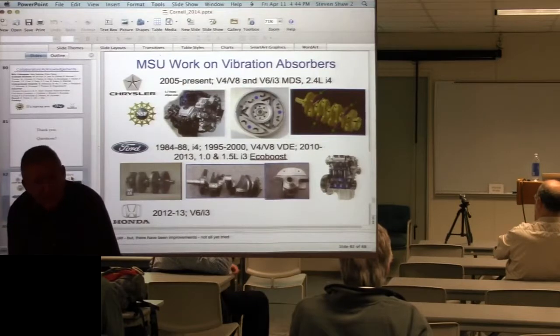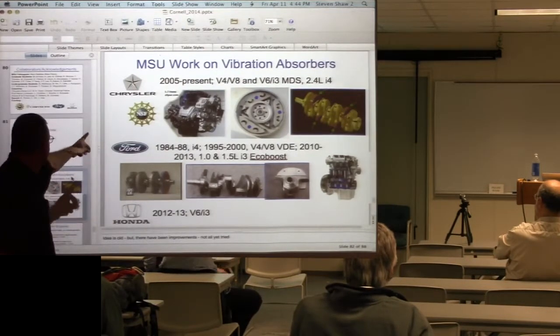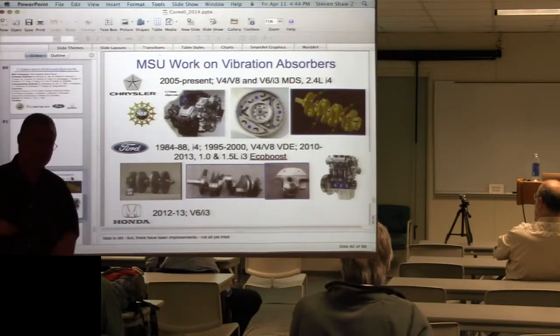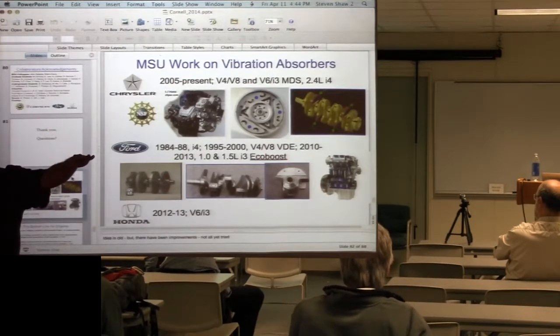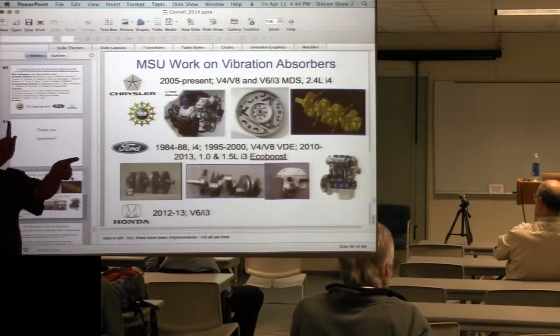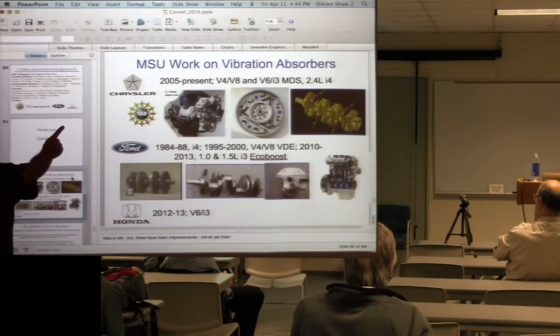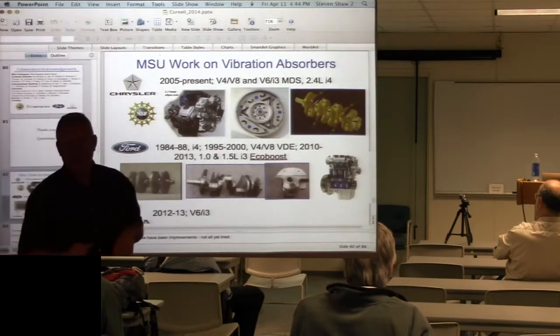Yeah, I agree. And that's exactly what our next project with Chrysler for this year is. We've looked at the linear theory. It's actually very interesting because you have order-tuned elements, constant frequency elements, which means you get eigenvalues varying. And it turns out that the undertuning business actually allows you to design the absorber to shoot the gap between the eigenvalues and not have a resonance. Because anytime you have an order excitation line that crosses a natural frequency line, you get a resonance.